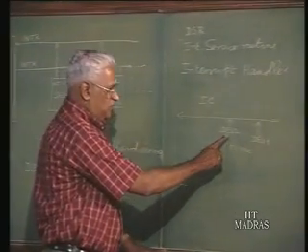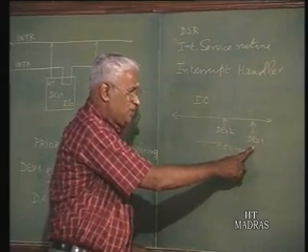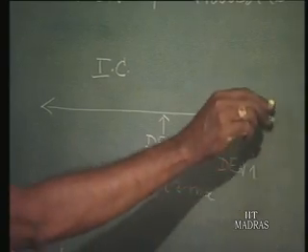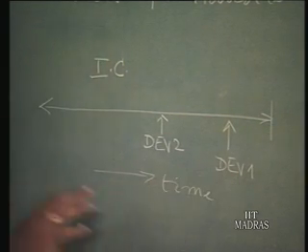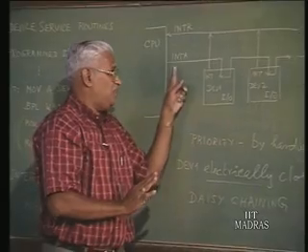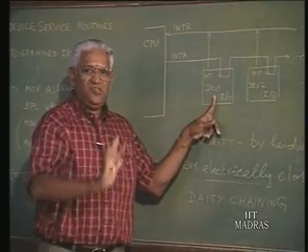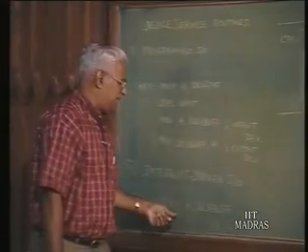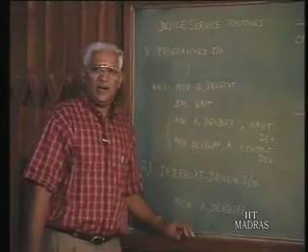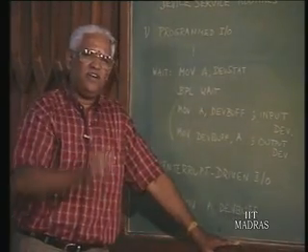Device 2 generated the interrupt and then device 1 generated the interrupt, and at the end of the instruction cycle, when the interrupt acknowledge is generated by the CPU, it goes to device 1 first, and so device 1 service is taken up. Now, we had assumed a simple one line interrupt service program. Now, assuming that this consists of say some 5 instructions.